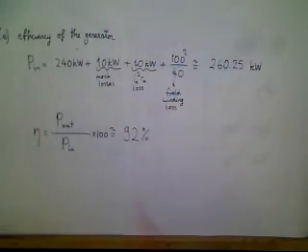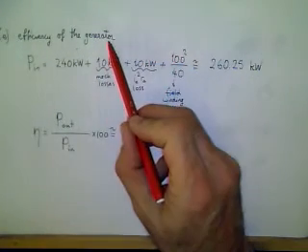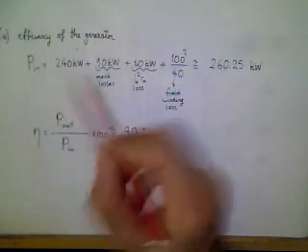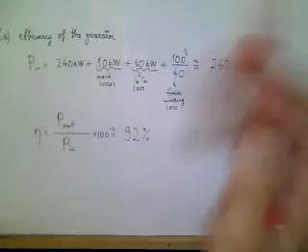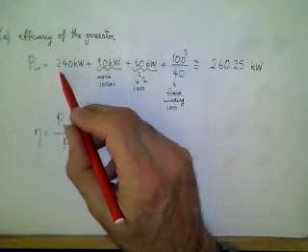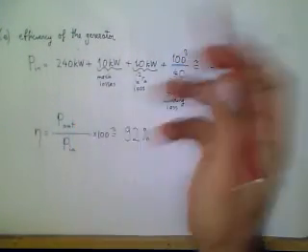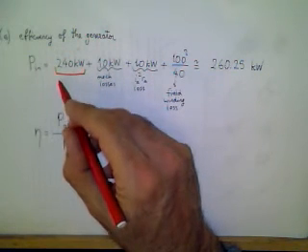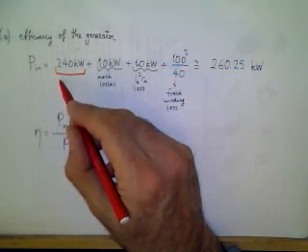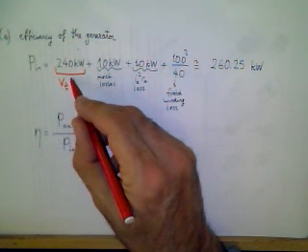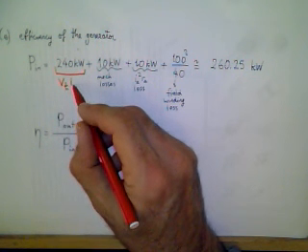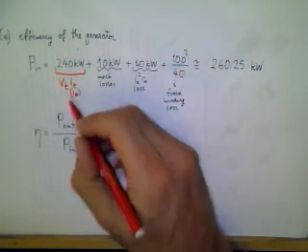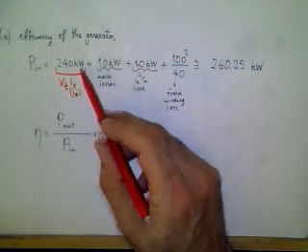So we can calculate the efficiency of the generator because we have net outputs and losses, etc. The total power input to the system from the mechanical side is the sum of all powers and losses. This 240 kilowatts is the output at the load, V terminal times I terminal, or this also equals I sub A. So it's the rated power output at the load.